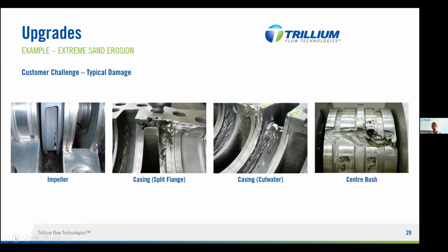One of the more common things that we would see in this type of application is this issue at the cutwater. As the fluid comes out of the impeller, this is the first thing that the fluid actually sees, and it just started to eat away at the leading edge of the cutwater and then work its way back. So you've got material loss going through the pump, which is not good.